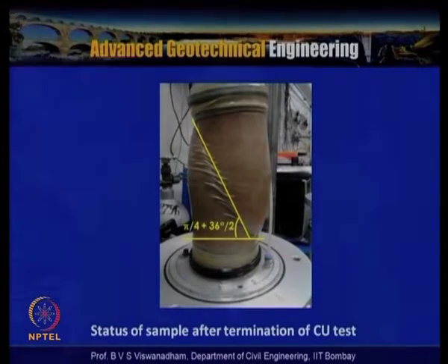In this particular lecture, we tried to understand the different types of triaxial tests, particularly the unconsolidated undrained, consolidated undrained and consolidated drained triaxial tests, and the unconfined compression test as a special case. All these tests were done for a compression case, and we know that by maintaining different combinations of cell pressure and axial pressures, we can also do extension tests using the triaxial apparatus. But in this case, we mostly covered the unconfined compression test and the UU, CU and CD triaxial compression test details, and we also discussed the stress paths pertinent to that with q, p and p dash.